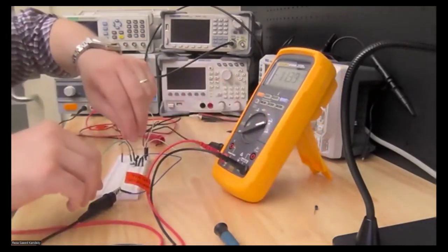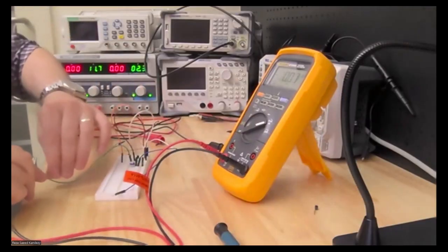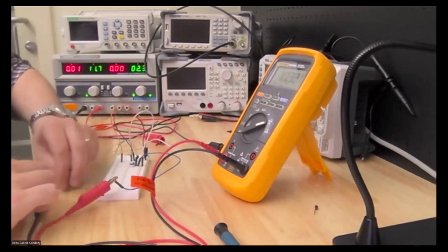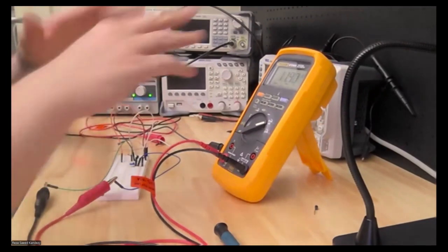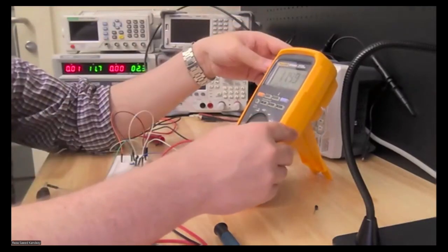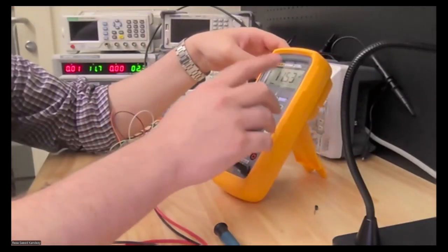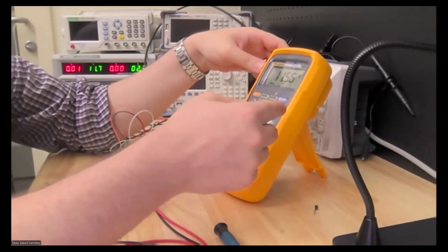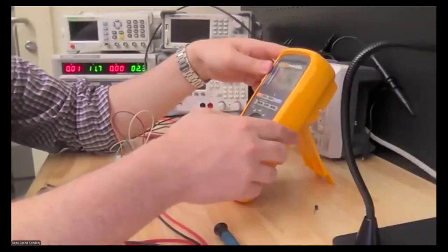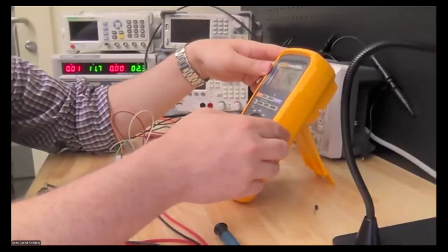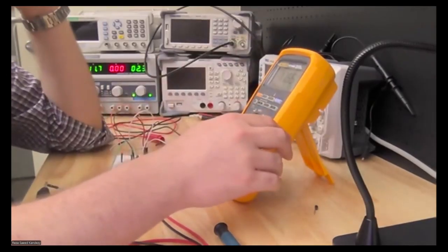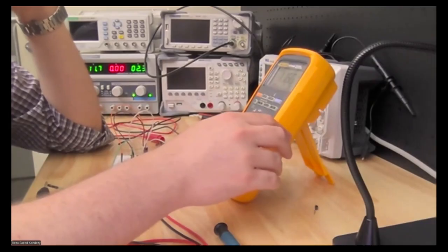Now you see, I connected the probes by mistake. No, no, this is the polarity. It doesn't matter. Here is a minus sign. Still the amp is okay. Now the ampere in the collector current, as I read, is 11.62 milliamp, which is very close to the simulation that we are going to have.